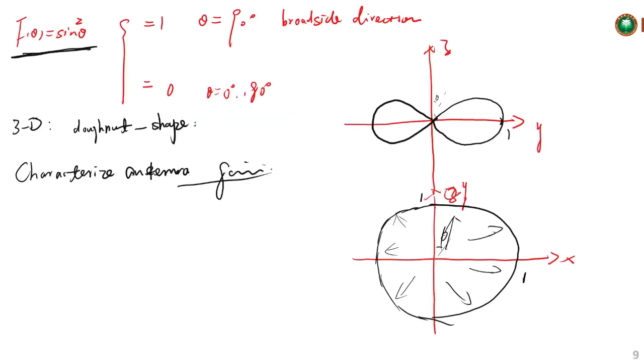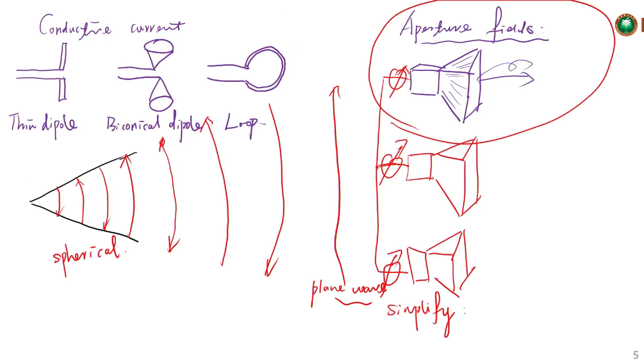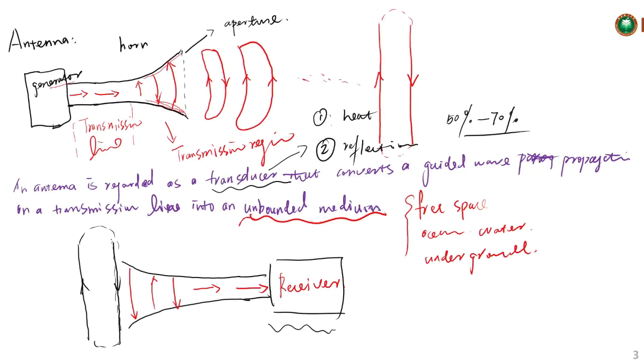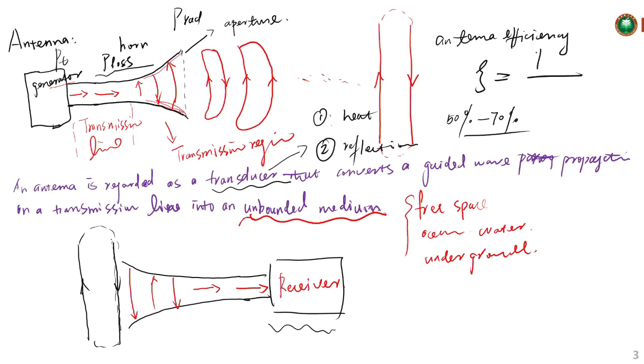So if we come back to our previous presentations on this one, the generated power here is the transmitted power here, and the radiated power is here. So during this process, there is some power loss due to the propagation of it. So that's why we define the antenna efficiency. We call it psi. It equals the radiated power divided by the transmitted power.